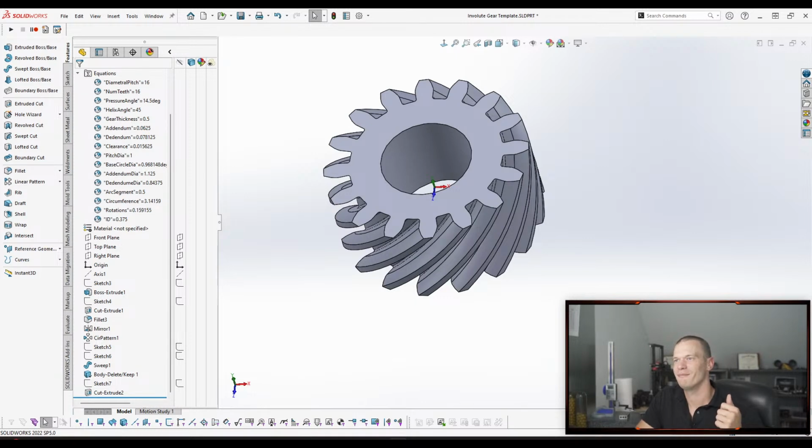Anyways, yeah, so going back to whether or not you should build top down or bottom up, always, if you can, build top down, in my opinion, right? The only time I would ever do something bottom up is if a design is locked and you're modeling something that you don't think is going to change. But even then, I can talk myself into doing top down anyways, right? I would always model in relationships if you can.